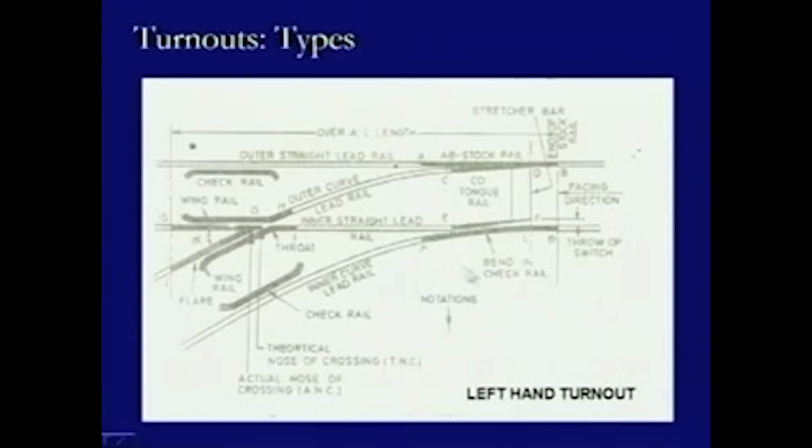Now, similarly, when you come towards the points on this side, there is one rail section like this, where there is some bend in the rail section. Similarly, there is one rail section which is provided on this side like this, a straight portion, and this is known as the stock rail. So, we have the stock rail here, we have the other stock rail here. Then there is a rail section which up to this portion is curved, and after that it becomes straight.